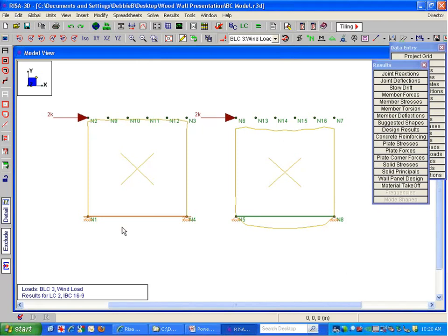First of all, it's unlikely that you will have an elevated boundary condition that allows such a deflection to happen underneath the sill plate of your model or your wall. So that's an odd thing that we're seeing, that we freed the one side here just so it would match our hand calculations, which it does nicely match, but that's not quite what happens in reality. More in reality, you've got a boundary condition at the bottom. The entire thing is supported, and then it actually is distributed by those supports there.